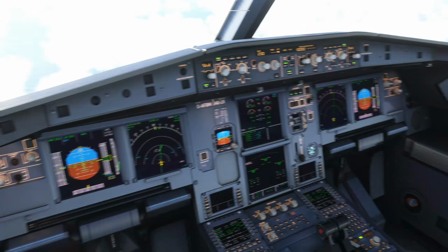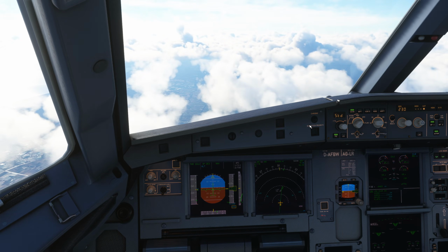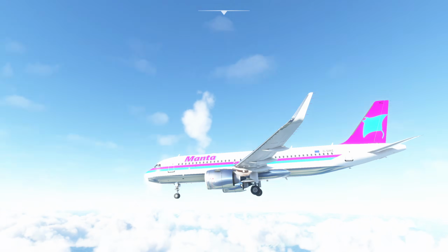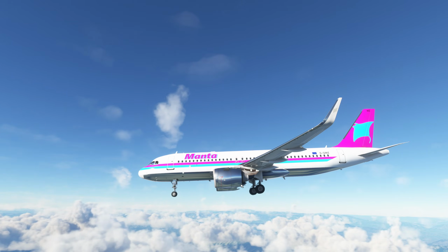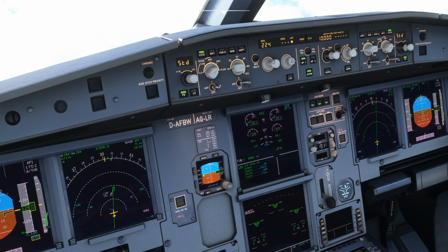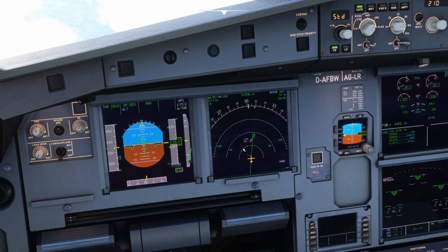Excellent modelling by Fly-by-Wire that we actually have that rumble in the background. I really like that, which it would be very noisy. We're also in open descent, so look how the aircraft now can just dive down. It's like better than the speed brakes. There it is. But nothing wrong with what we've done. Let's now bring the speed back to 210, which we can do, and then once we're back there we can actually raise the landing gear.